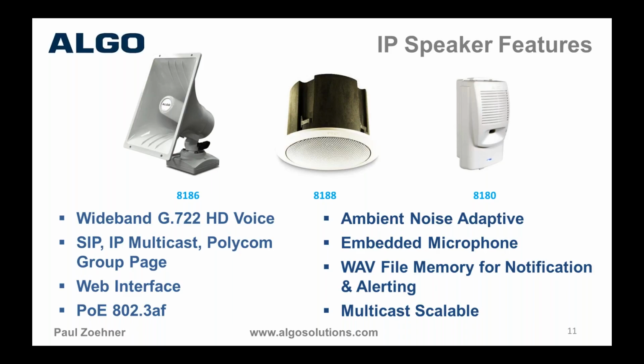They all support wideband G722 HD voice. Just like the paging adapter, they support SIP, IP multicast, vendor-specific interfaces and protocols. They're all administered through a web interface. If you poke the reset button after boot up from the device, it will speak its IP address to you. For example, one IP address is 192.168.